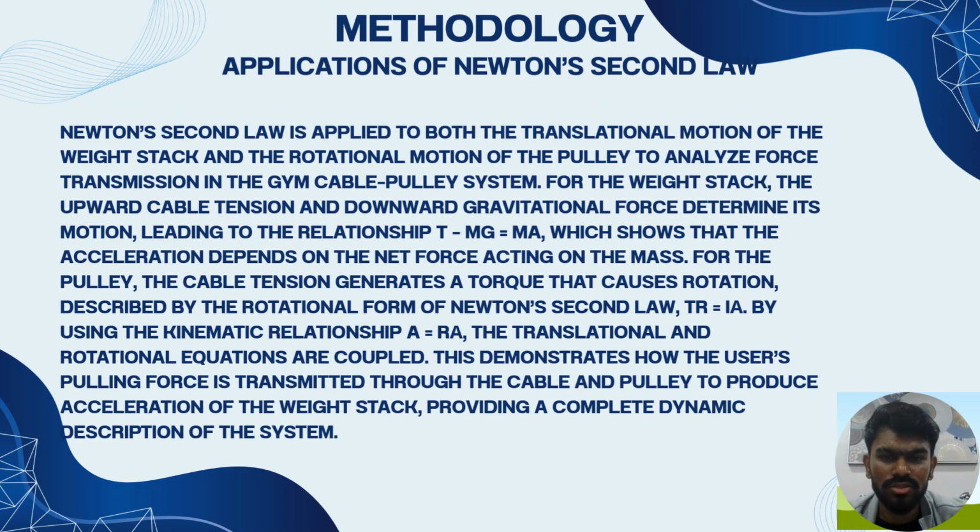Finally, the application of Newton's second law. Newton's second law is applied to both the translational motion of the weight stack and the rotational motion of the pulley to analyze force transmission in the gym cable pulley system. For the weight stack, the upward cable tension and downward gravitational force determine its motion, leading to the relationship T minus mg equals ma, which shows that acceleration depends on the net force acting on the mass.